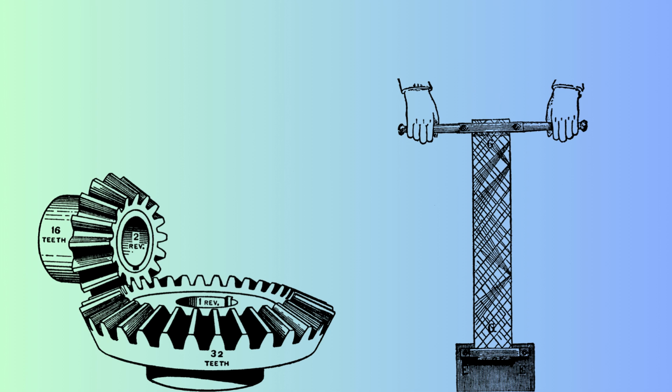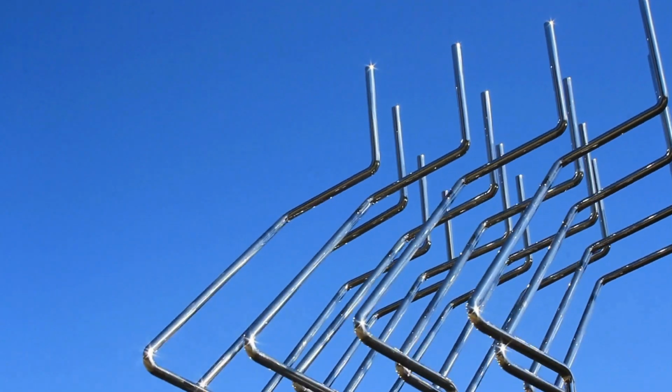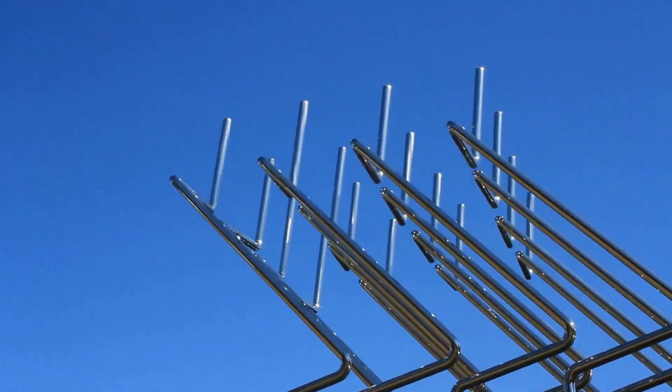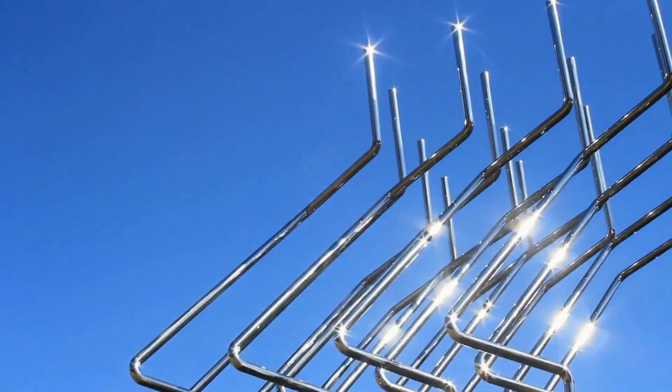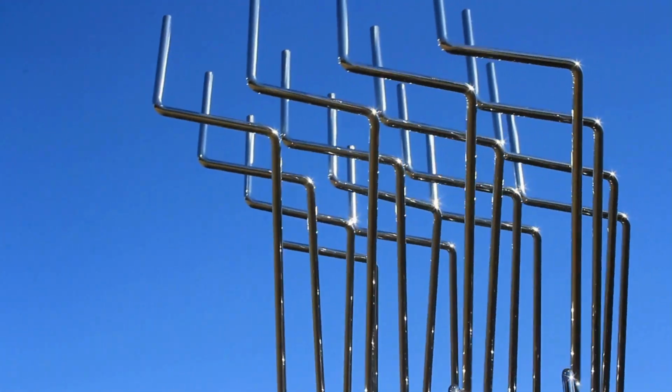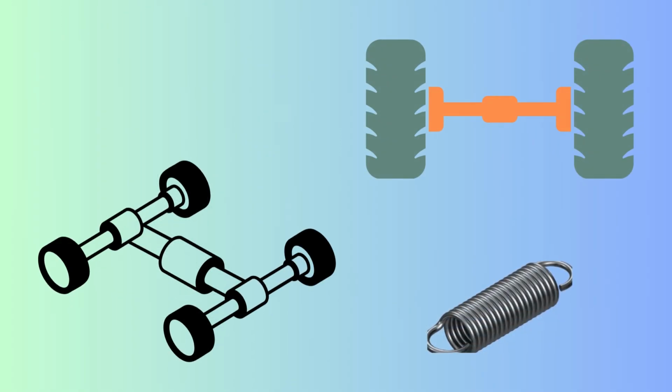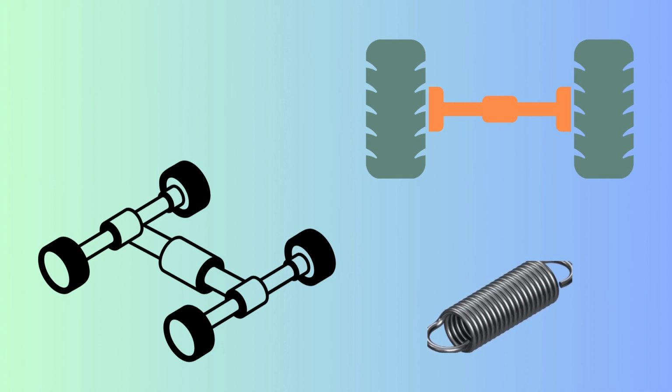When a torque is applied to a shaft, it creates a twisting moment, causing the shaft to rotate. This twisting force induces shear stresses within the shaft, which are greatest at the outer surface and decrease towards the center. The shaft deforms, twisting or rotating about its axis, resulting in an angle of twist. Some factors like rigidity, shape, size, and dimensions affect torsion. The material shear modulus, G, and torsional rigidity influence the shaft's resistance to twisting. The shape and dimensions of the shaft's cross-section affect its resistance to torsion. The magnitude of the applied torque determines the shear stresses and angle of twist.